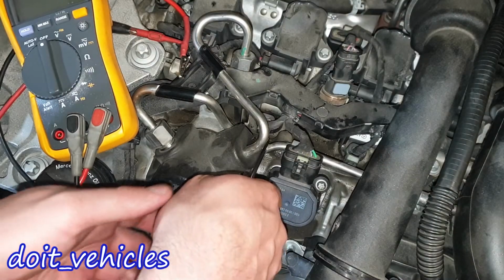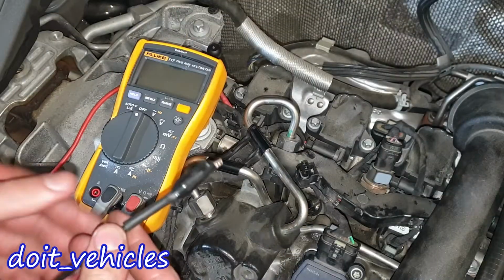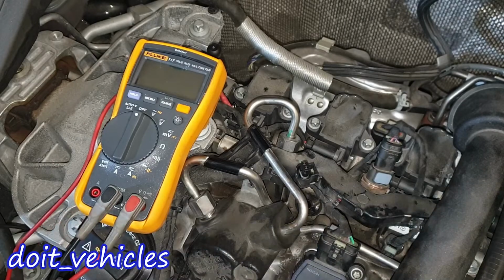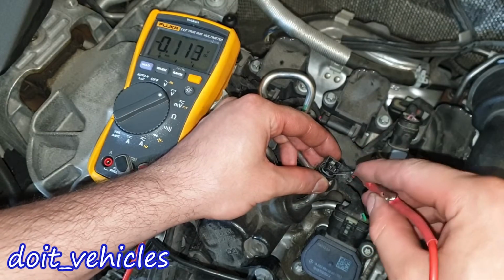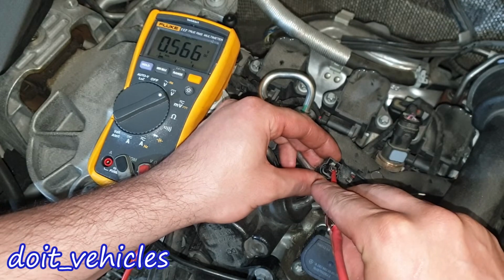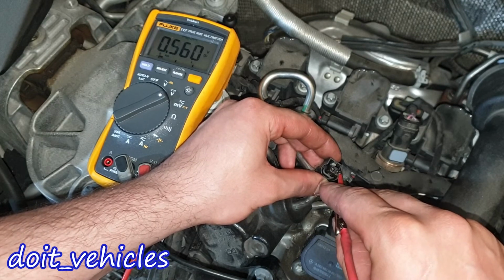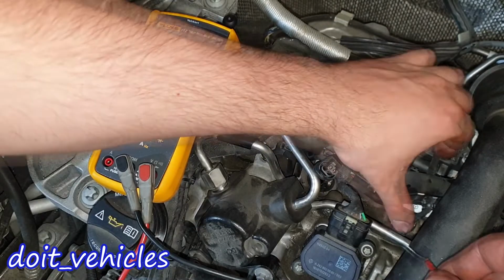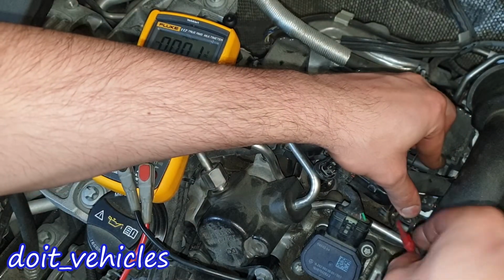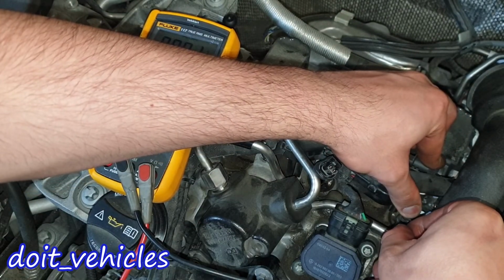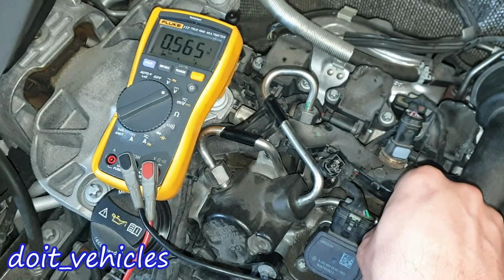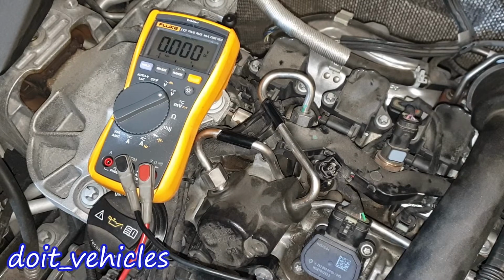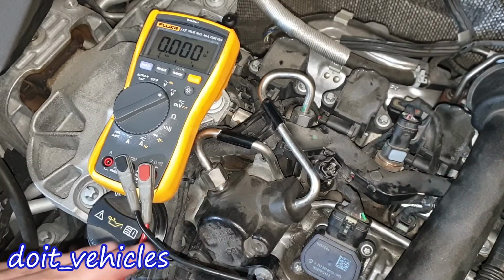Okay, so let's unplug the connector. Let's connect the voltmeter terminal to the ground. Now let's see, I'm going to turn on the ignition, holding it with the clip here on top. Let's start with the left pin. We've got 0.5 volts, the second pin 0.5 volts. Now I'm not going to plug it back, I will back probe the connector on the other injector. 0.5 volts again. See the second wire, 0.5 volts again. On most injectors we're going to find 8 volts sometimes, but I think that was from a regular injector.